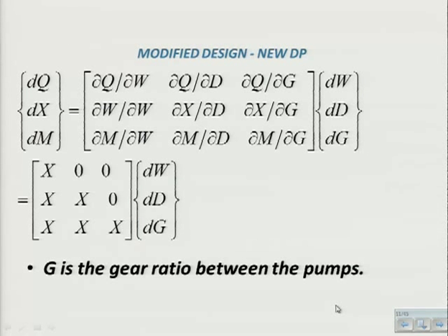So here is our design matrix written in terms of partial differentials. And we shouldn't be concerned that, oh, I don't remember all of my calculus. All you need to do is remember that this term in this matrix is telling us how the flow rate changes with respect to changes in the, what was W? The pump speed. And now we don't actually need to be able to evaluate these precisely, all we need to do is tell whether it's a 0 or a 1.